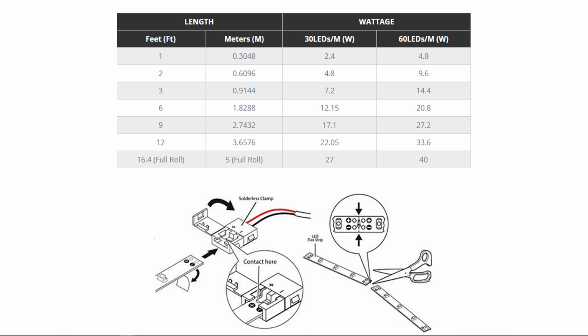But you can determine exactly how much power you need, what size power supply. Typically, these strips are 12 volts DC. So to determine amperage, you divide the power by the voltage. That gives you the amperage. Power divided by voltage. So power equals E times I, current times voltage. So you can transpose that around and determine any of the others.